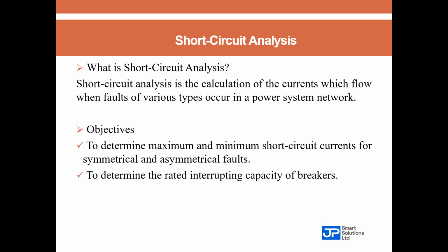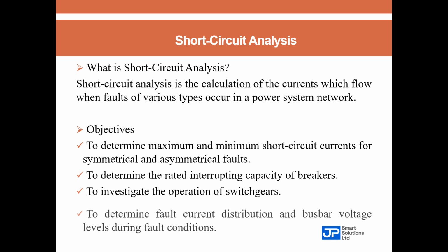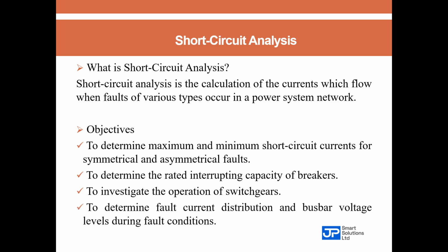The next objective, short circuit analysis helps us to determine the rated interrupting capacity of our circuit breakers. Very important. Next, it helps us to investigate the operation of our switch gears, our protective devices, our circuit breakers, our fuses, our relays. Short circuit analysis also helps us to determine fault current distribution and bus bar voltage levels during fault conditions.